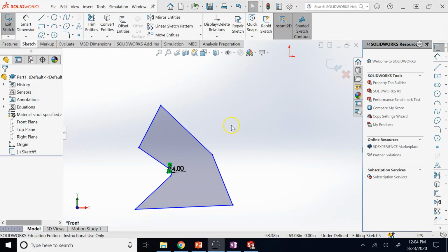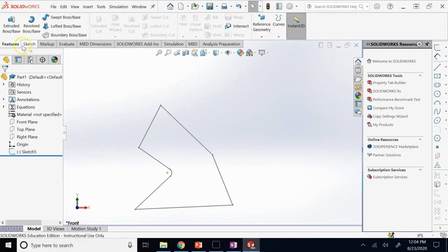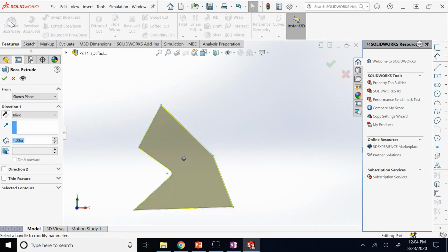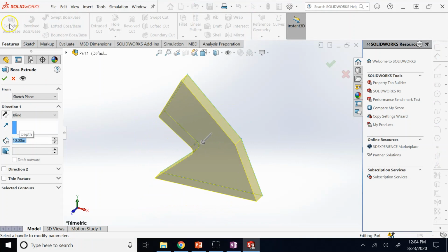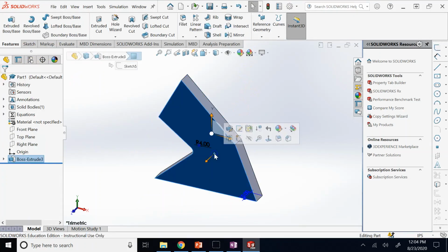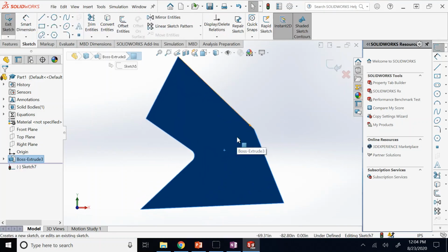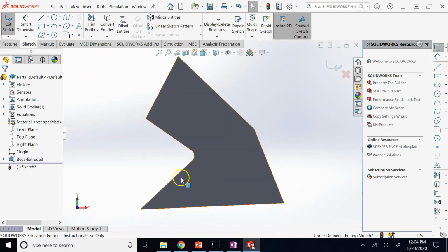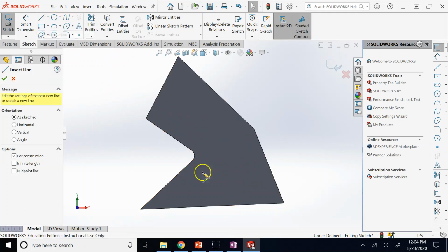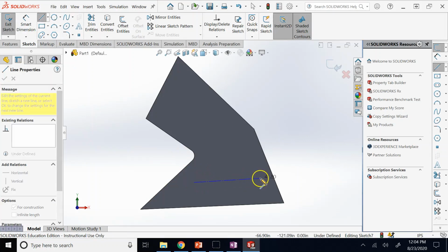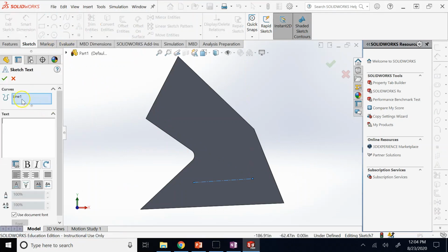hard. So here, let's say you made this sketch and then you used it to create some parts of your own, and then on this part you want to add the logo of your company, right? So you go on this top surface, you create a sketch, and then you want to write something here on a line or on a curve. So you go and use basically a line, right? A center line. It has to be a center line. And then you use the text, and now it uses this line to write on, right?